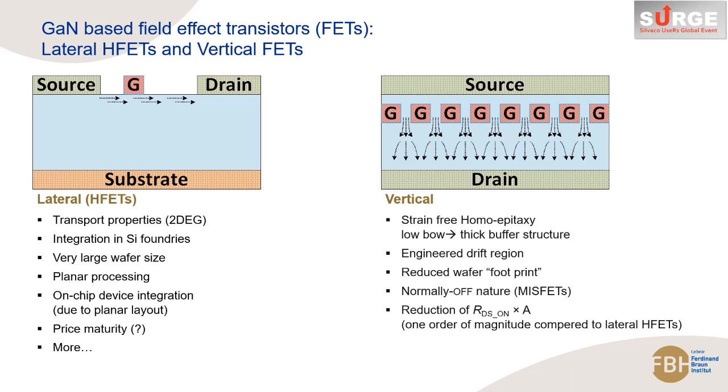Vertical FinFETs are strain-free homoepitaxy grown on freestanding GaN substrate. These allow epitaxial growth of thick drift regions. Therefore, they have a reduced footprint with reduced specific on-state resistance, one order of magnitude lower compared to lateral HFETs.